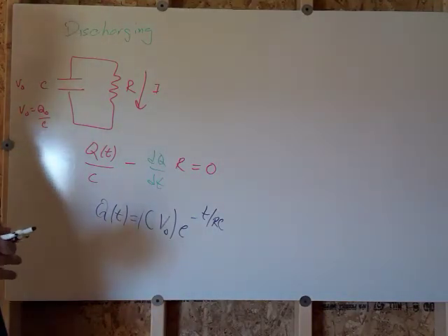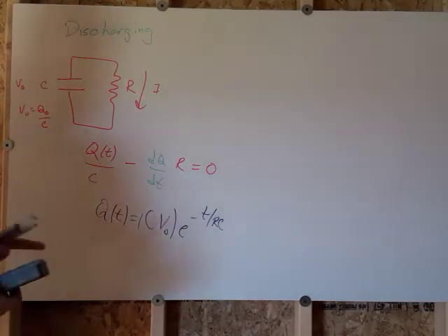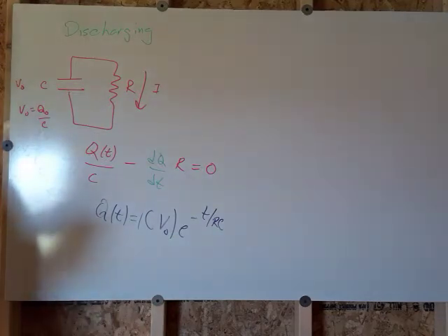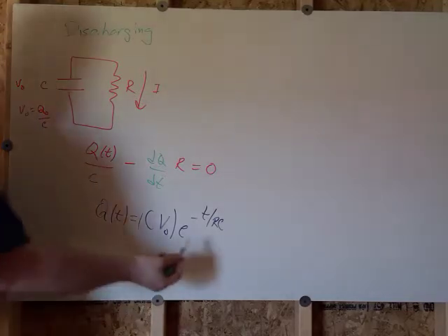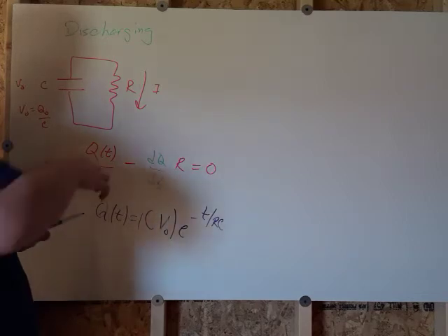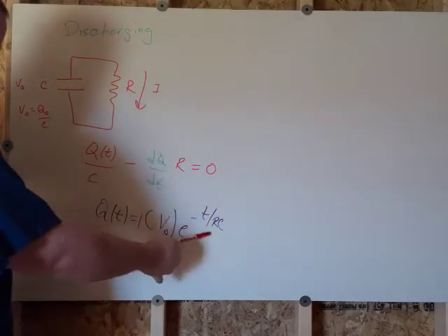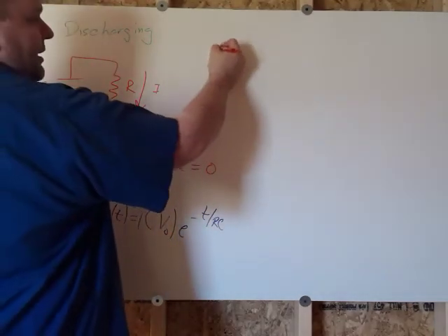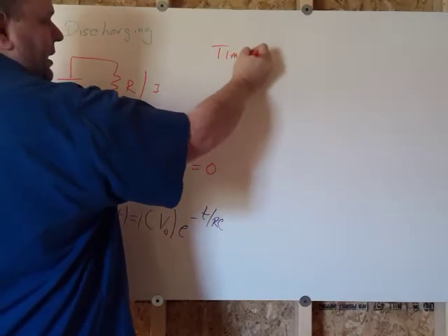We don't know what the sine of a meter is or what the exponential function for 12 newtons is. All the units have to go away. So R times C shares the units of time. And the idea is this R times C, we can define a time constant